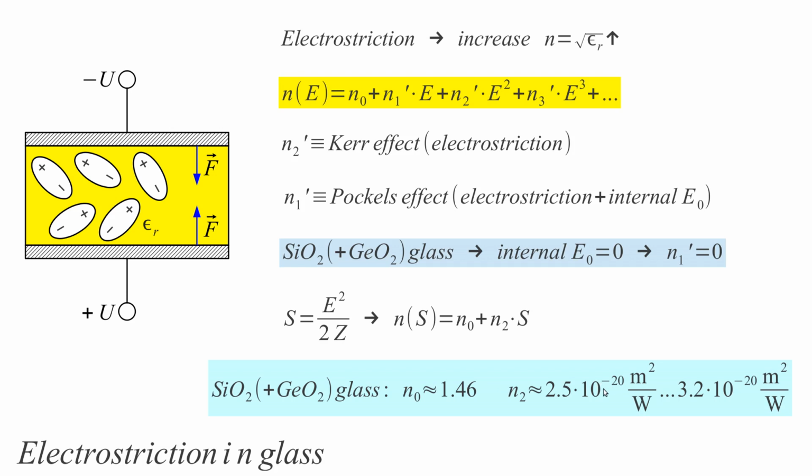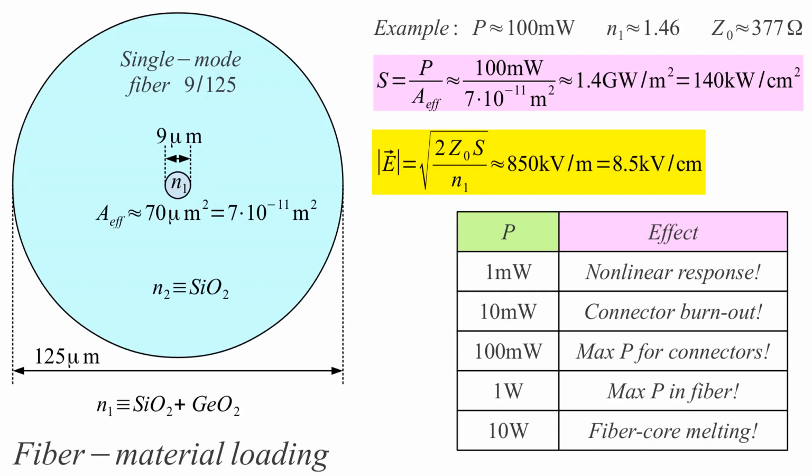And we have 10 to the 11th power of wavelengths per 100 kilometers of fiber. So 10 to the 11th power and 10 to the 9th power, this minus 20 cancels out. And these things become observable, becoming also a nuisance or something useful, the way we are looking at it. But we cannot neglect nonlinear effects at high power communications, especially when we are above say 1 milliwatt or above 10 milliwatts. Here we should no longer neglect nonlinear effects.